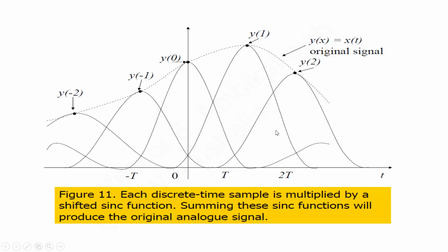With this, I have explained the process of how an analog signal can be converted to a digital signal in my previous lecture. And in this lecture, I have covered how you can recover the original analog signal back from the digital signal using a D2A converter and passing the output of the D2A converter through a low pass filter, which we call the reconstruction filter.